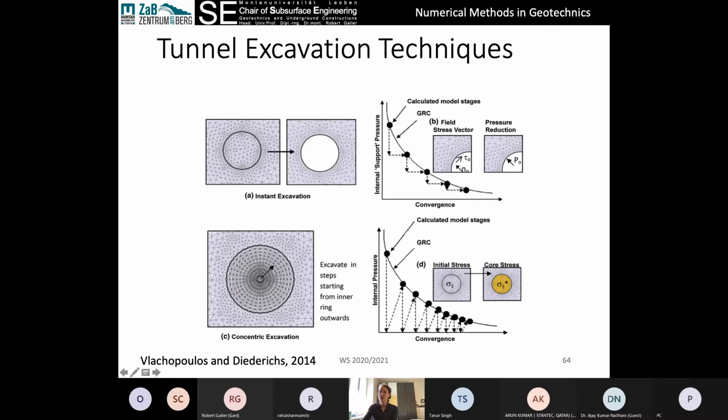Then we reset the pressures. So the pressures are reset to zero when we replace the material. Because this material is less stiff, it deforms and acquires a little bit of pressure from this material deforming, pressing on this, inducing a pressure inside this material. And we get this point here. And then we replace it again, set the stresses to zero, and then slowly the stresses increase with an increasing deformation, and so on and so forth until we solve down this smooth curve using these individual steps.